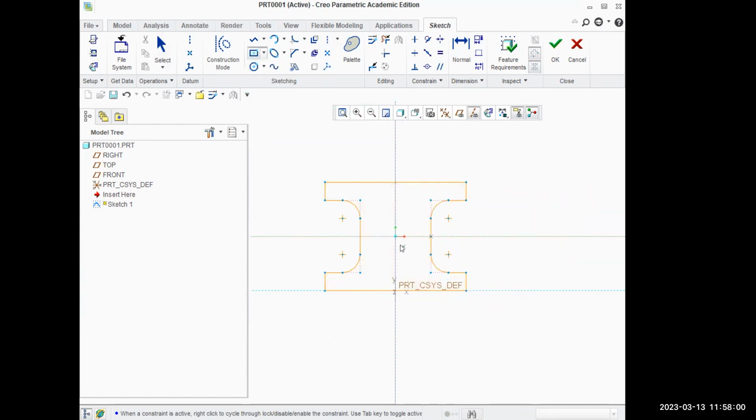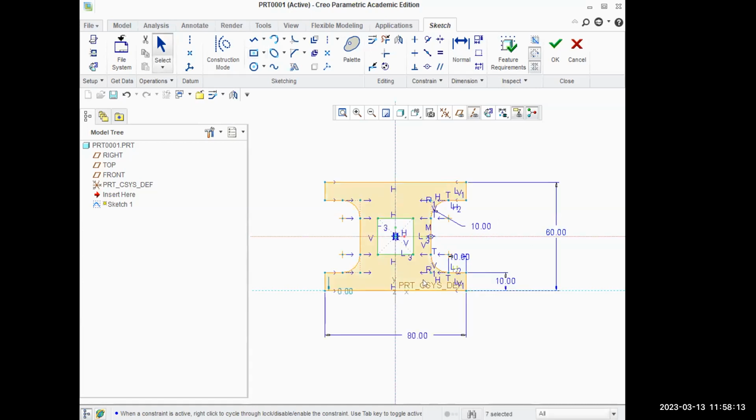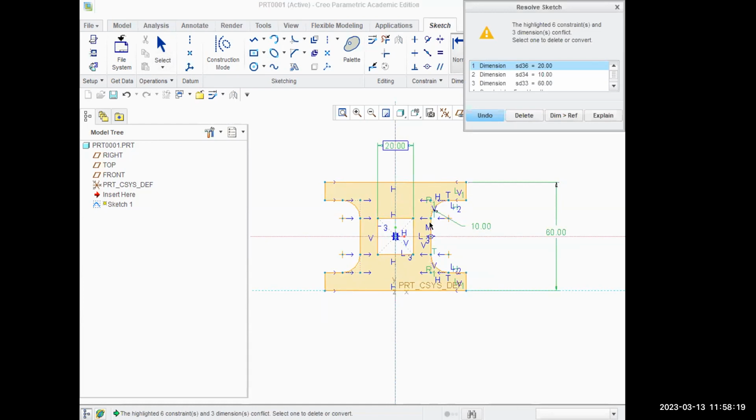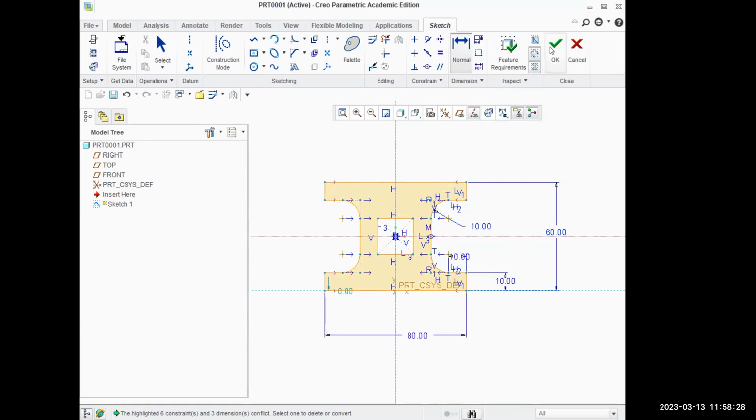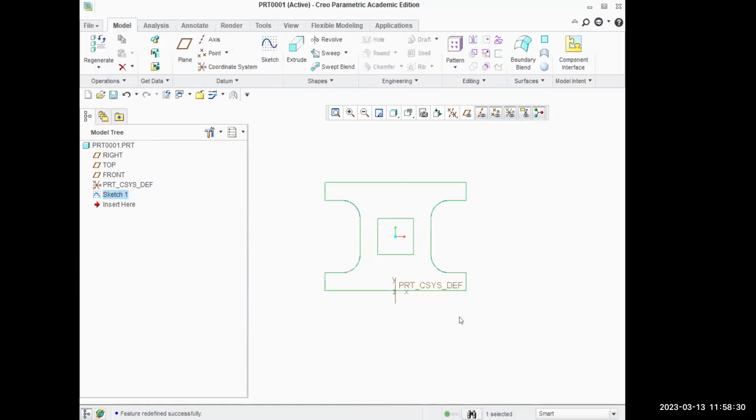I am selecting center rectangle and dropping the dimension here. Here you can see again I can make use of L and L, which means a square. If you want to draw a square, at that moment you just give a click, and it will drop as a square. Then you just drop the dimension for this one. Already, I think the tracking of these 2 points, at that moment I might have selected, that's why it is already showing 20. So you can come back now, say okay. So this completes your job.